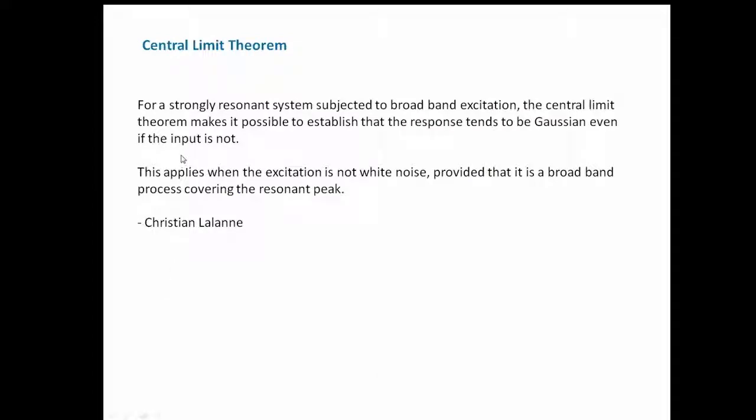But here are some observations from Christian Lalanne, however he might pronounce his name. For a strongly resonant system, such as our spring mass system, subjected to broadband excitation, the central limit theorem makes it possible to establish that the response tends to be Gaussian even if the input is not.